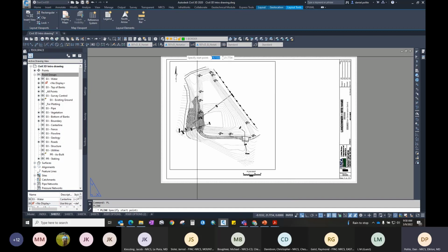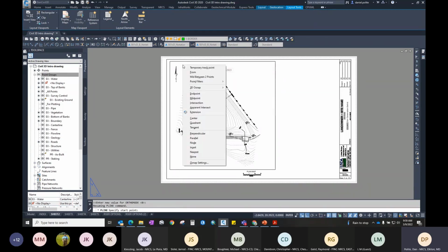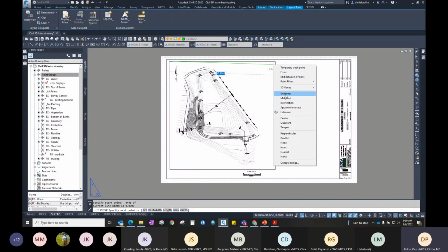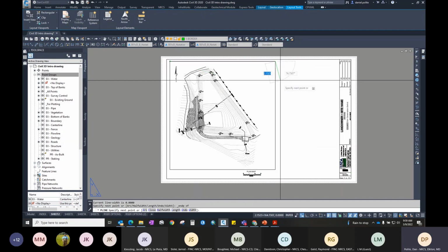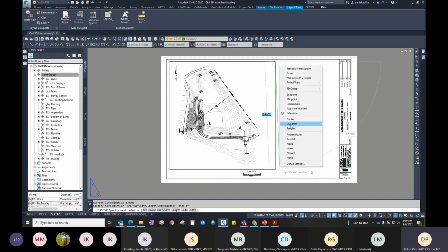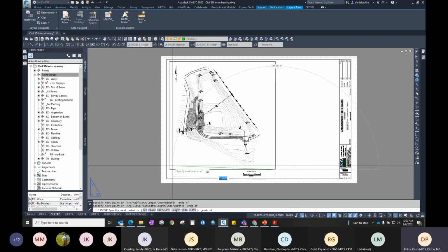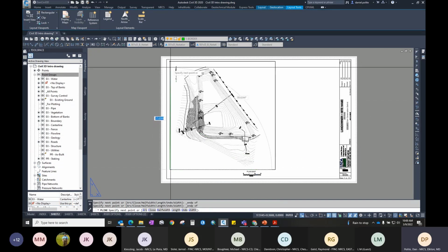So I'm going to do a polyline. Have your object snap on, shift, right click, endpoint. And then to go to the next endpoint, shift, right click, endpoint, shift, right click, endpoint. Now this is a cumbersome way of doing it, and then hit C for close.